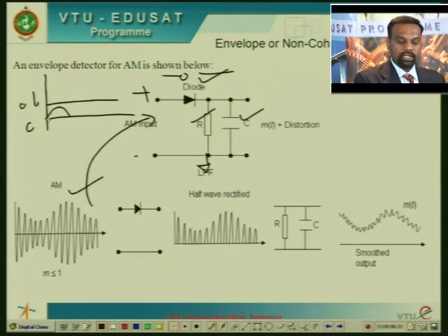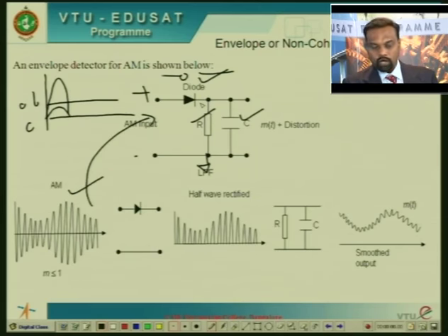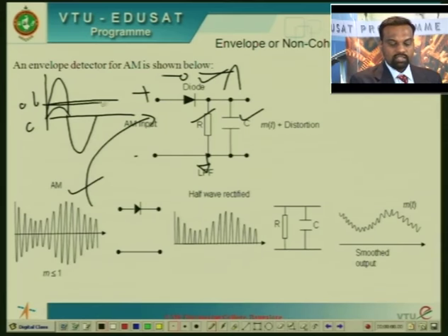Suppose your input voltage is anything greater than this, what will the diode do now? Because the input voltage is greater than the cut-in voltage, the diode will be switched on. Because the diode is switched on, the output that comes out of the diode would basically be the positive voltage. Suppose you apply a negative voltage across the diode, because this negative voltage is less than the threshold, that is the cut-in voltage, the diode will be switched off. Because it is switched off, the output will again be equal to 0.